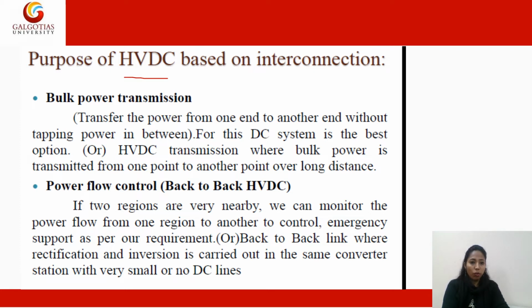Then power flow control with the back-to-back HVDC system, where both the converters, rectifier and inverter, are placed at one location. That is also used to control the power flow. This connection of the HVDC is called a back-to-back HVDC system.